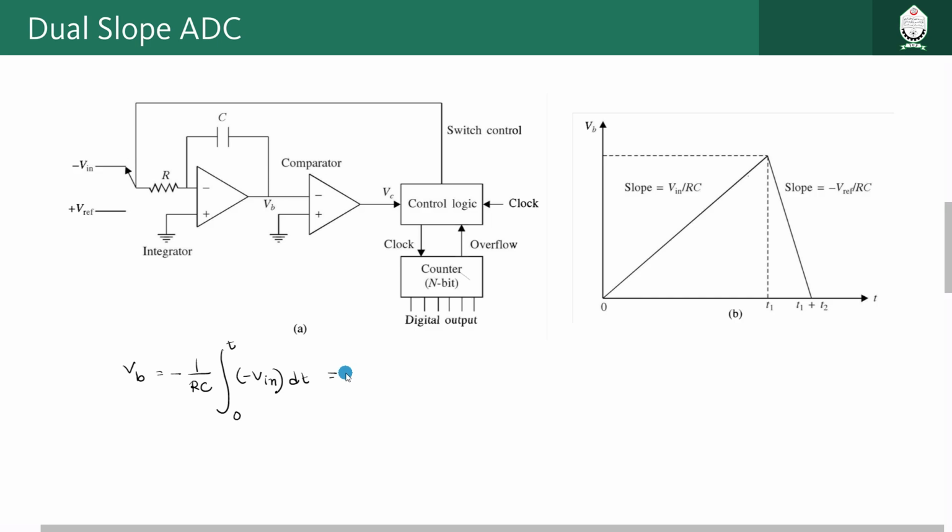But let us try to understand what happens initially whenever the circuit initiates. We will have this voltage coming here. This is the input voltage, right? Everything will be in reset condition, so there will be no charge stored in the capacitor, so VB will initially be 0, just like here. You see in this graph with respect to time how the voltage VB is changing.